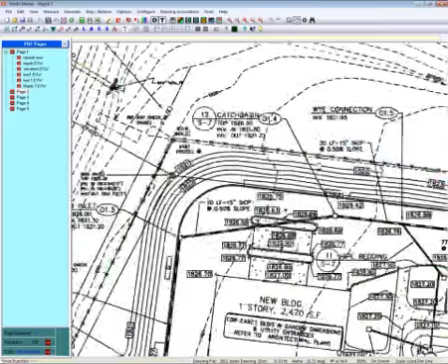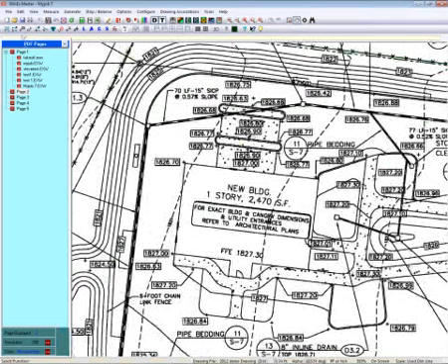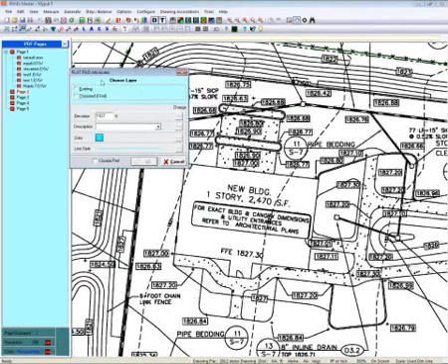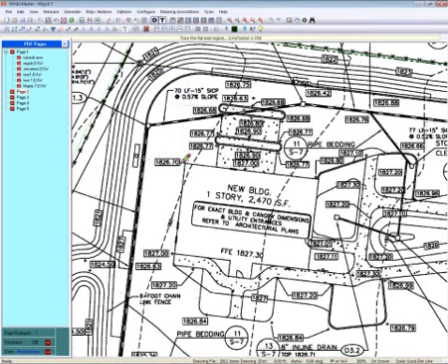But I know most of you do pads, so let me show you how easy it is to do a pad. You click on the pad icon, and we'll do a proposed here. This one's at 1827.3. I'll stay with the red color. And here you don't have to hold your mouse button down. Just click where the pad changes direction. You can hold your left mouse button down and drag it if you want, but it's easier, I think, to do it this way. Let the software finish this off.